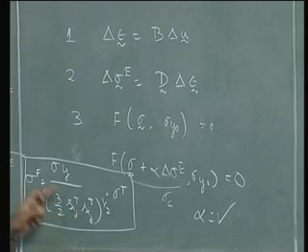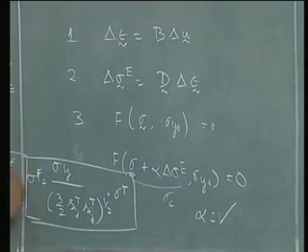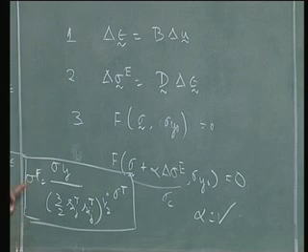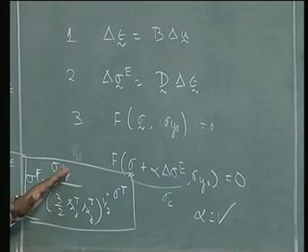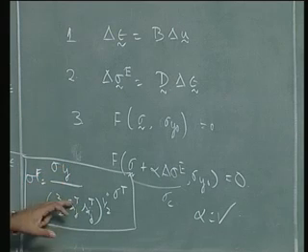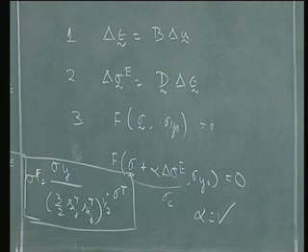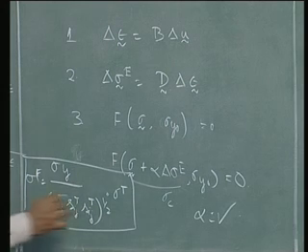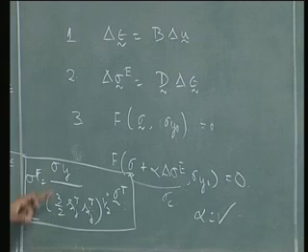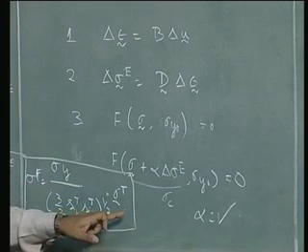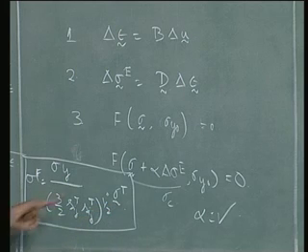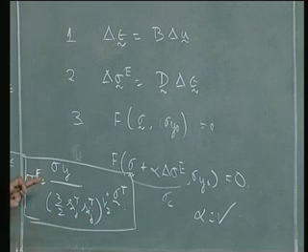Now with this new sigma f, if you calculate the yield function, you will see that you automatically satisfy the yield criteria, because this function would have done the trick. Is that clear? This ratio check is very simple and straightforward. This ratio is the one used to correct sigma t, so that the sigma final will lie on the yield surface.